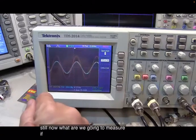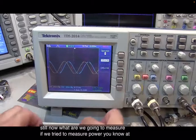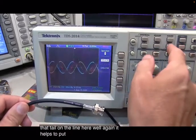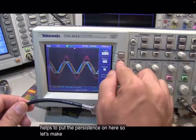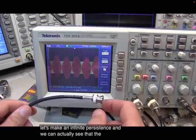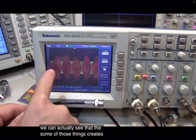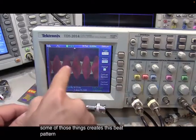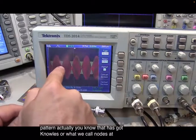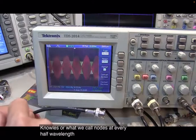Now, what are we going to measure if we tried to measure power on the line here? Again, it helps to put the persistence on. So let's make it infinite persistence. And we can see that the sum of those creates a beat pattern that has nulls, or what we call nodes, at every half wavelength.